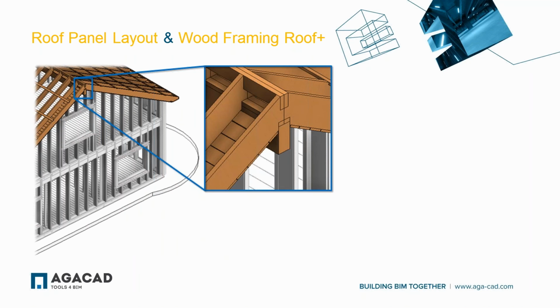And actually Wood Framing Roof Plus includes all different possibilities and options for how to frame the roof. For those who already work with the Wall Plus or with the Floor Plus, the procedure and the workflow will be totally the same. Just here you will be able to frame the roof segments, and it will allow you to have different options of framing where you will be able to add bridgings and blockings and different joists and so on.